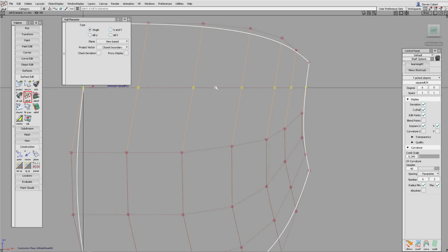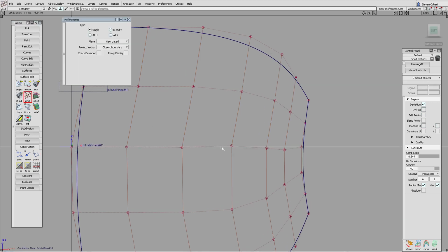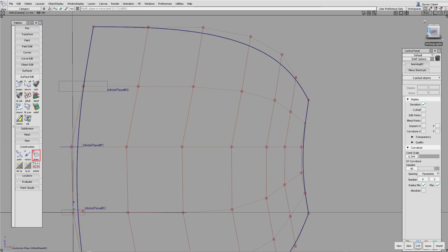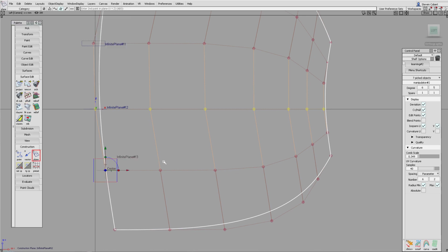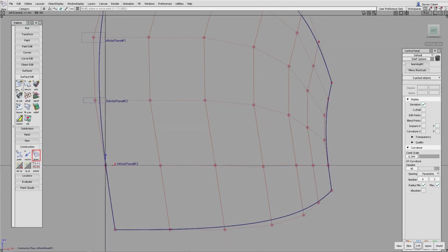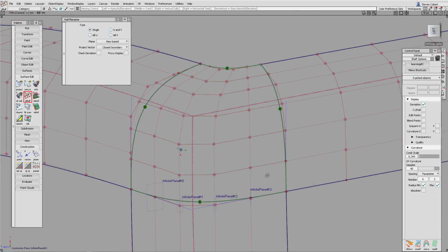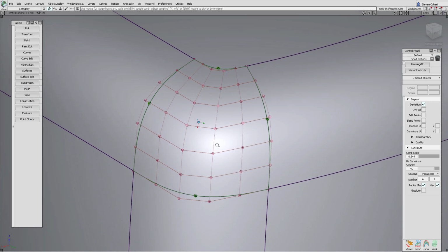Having planarized one of the hulls, we're simply going to repeat this process on all of the hulls. In other words, defining and setting a 3-point plane, going to the left view, and then planarizing the hull in this view. Any small errors in the edge continuity that we get, we can fix by moving CVs around. To complete the corner, we'll delete or hide the construction surfaces, bring back our trimmed fillets, and trim out the block surfaces. We'll also need to check that our corner is aligned with the trimmed fillets.